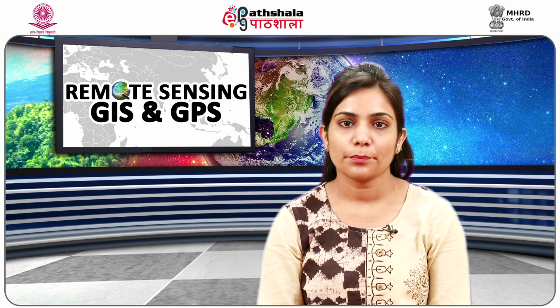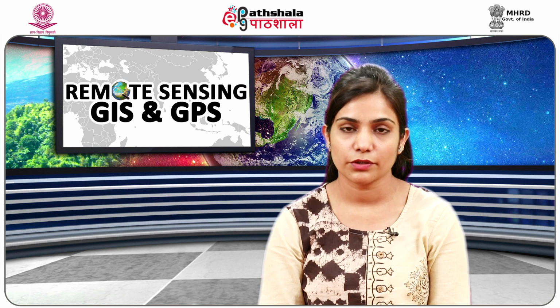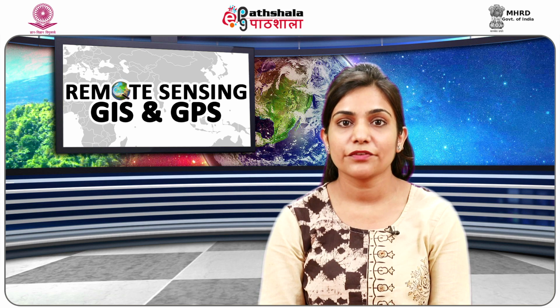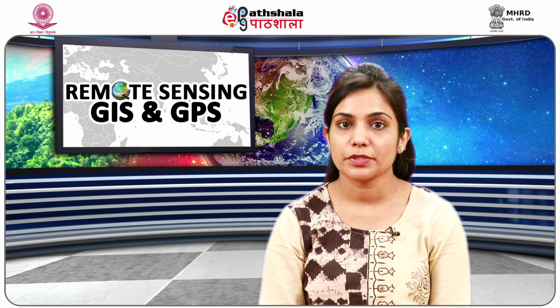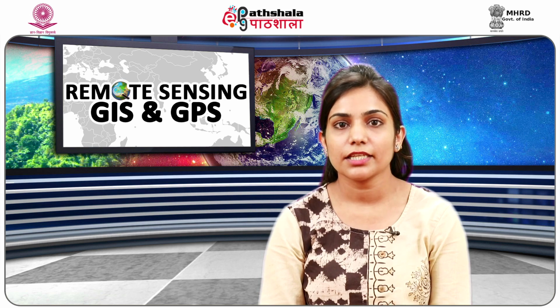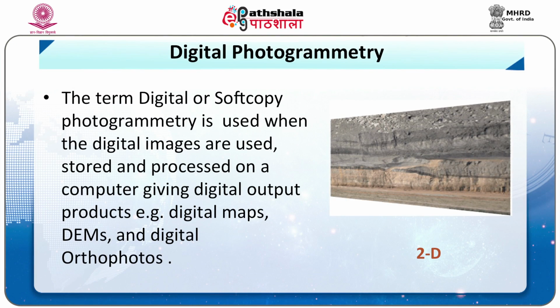With the advent of computing and imaging technology, photogrammetry has evolved from analog to analytical to digital soft copy photogrammetry. The main difference between digital photogrammetry and its predecessors, that is analog and analytical, is that it deals with digital images directly rather than photographs. The term digital or soft copy photogrammetry is used when the digital images are used, stored and processed on a computer and give digital output, that is digital maps, DEMs and digital orthophotos.